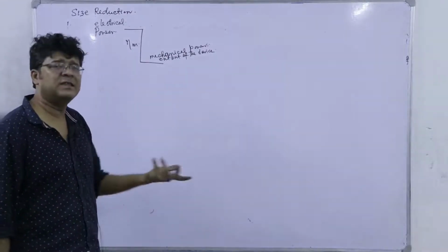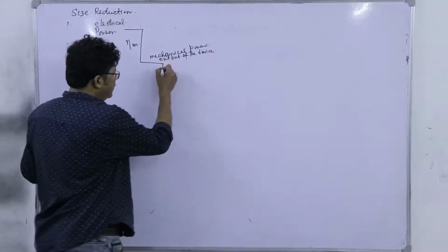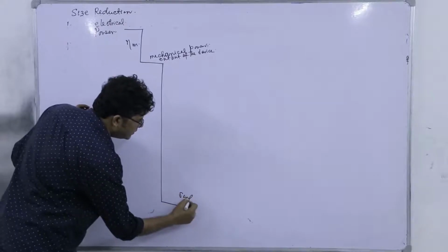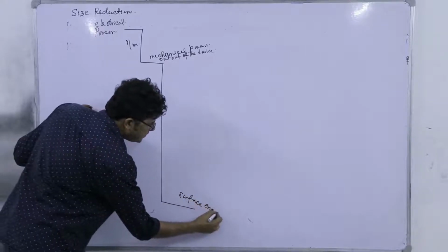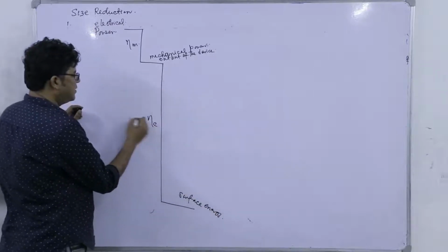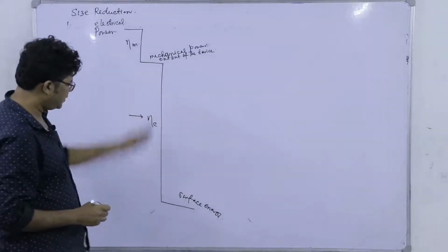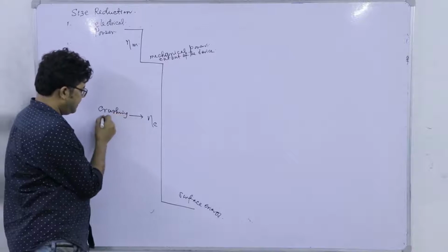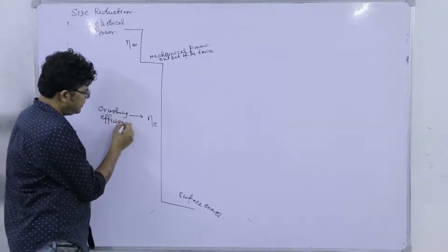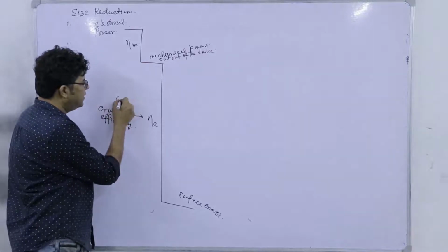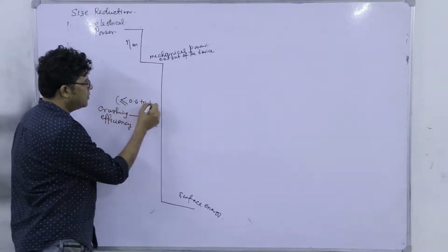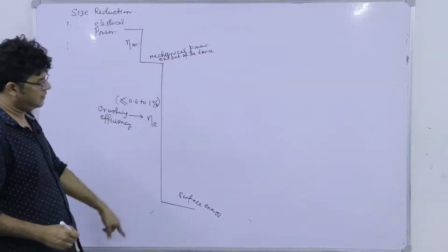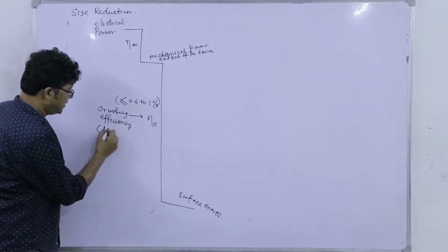It may be more than 90%. However, there is a huge drop, and finally it will deliver the surface energy. And here comes the empirical term. It's called the crushing efficiency, and this crushing efficiency is mostly less than 0.6 to 1%. So this cascade specifically is the source of non-ideality.